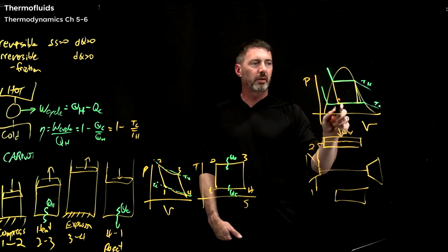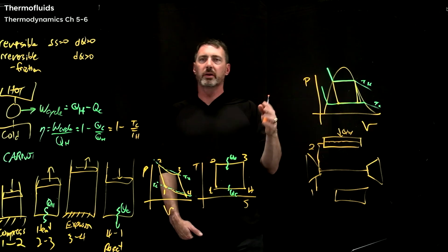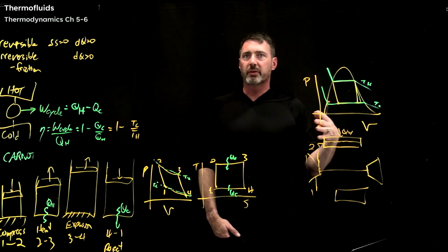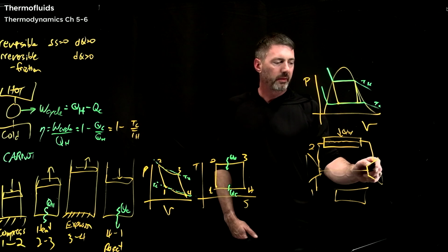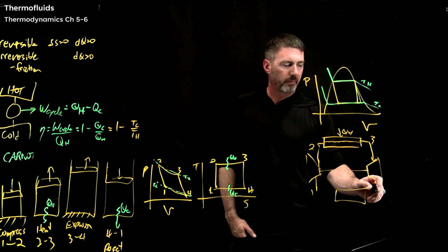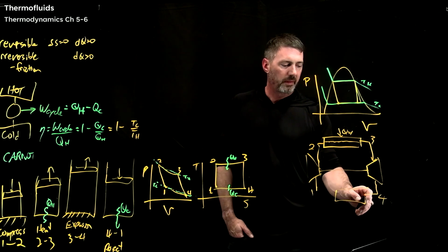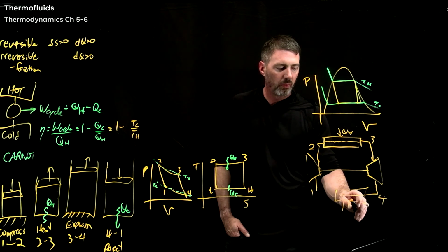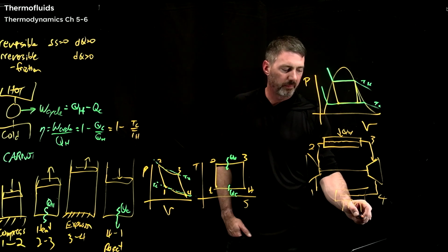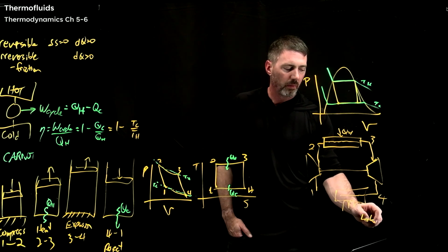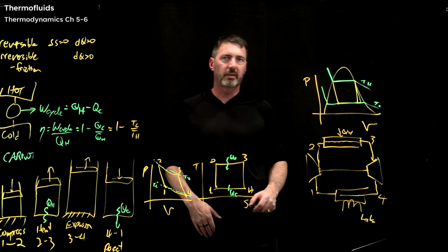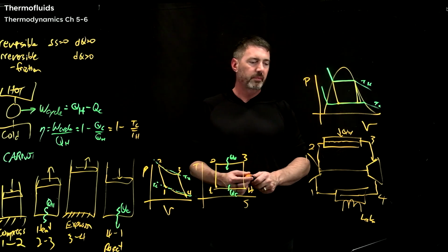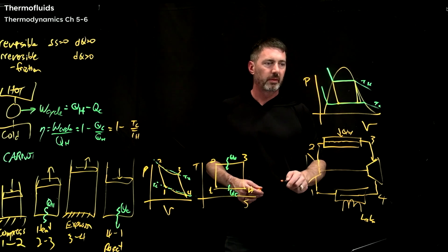So whatever you're burning inside of there, a boiler, you're burning coal or natural gas to boil that water, and then you're going to drive across the turbine, okay? And then you're going to cool down that water, maybe with a lake or air, an external heat exchanger to get back to the system. Now, a couple problems are going to occur with this, right?